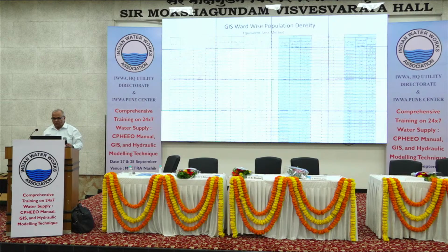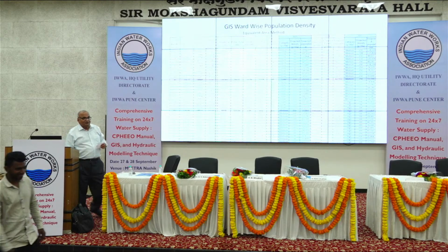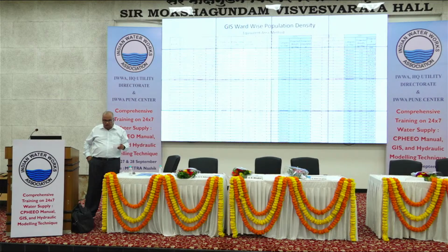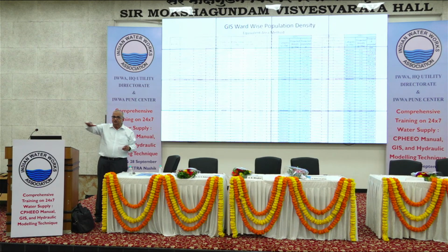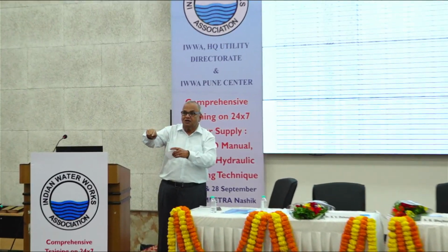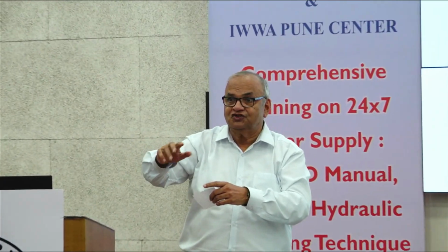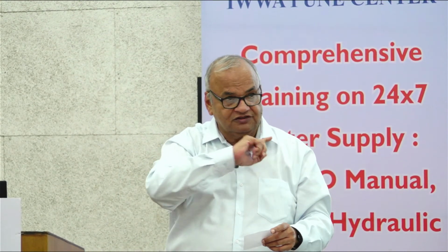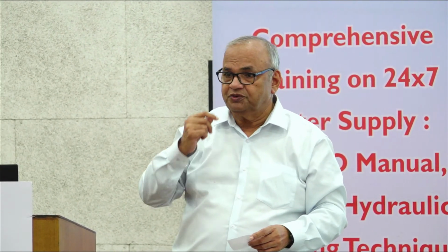Okay, we break here. And now this is very interesting, how the demand is given. After that, my line of action will be: you have given elevations to all the nodes, now you will be giving all the demands, future, after 30 years demand, to each and every node. Even for 15 years, the same procedure will have to be adopted.